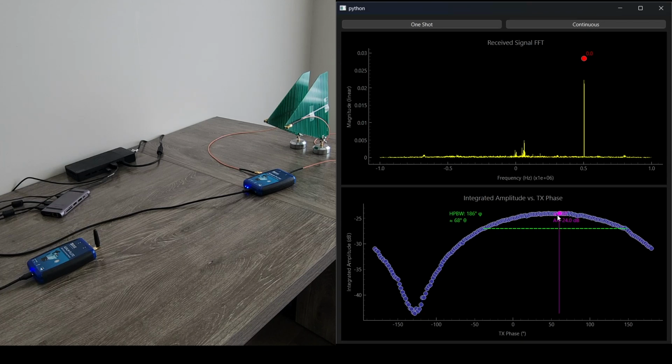First, we are going to look at the idea of beamforming and how it helps, and explore some math behind it. Then we are going to look at how we can enable the ADALM-Pluto second TX or RX channel for beamforming. Then we'll go over the code.